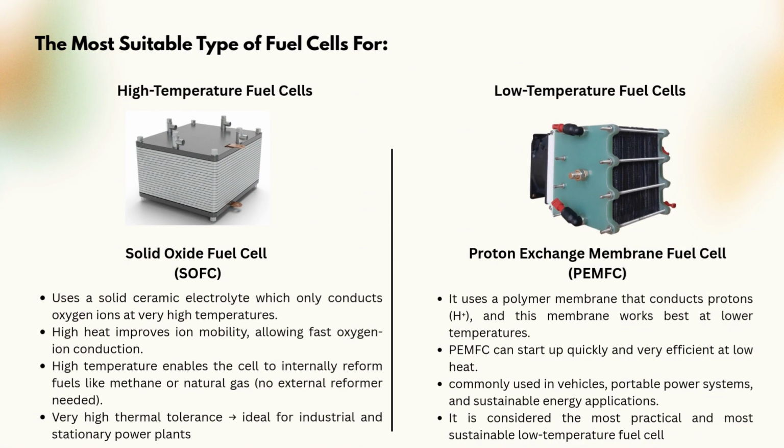And then the most suitable type of fuel cell for high temperature is the solid oxide fuel cell. It uses a solid ceramic electrolyte that only conducts oxygen ions effectively at very high heat. The high temperature also helps the fuel reforming process and makes it ideal for industrial and stationary power.